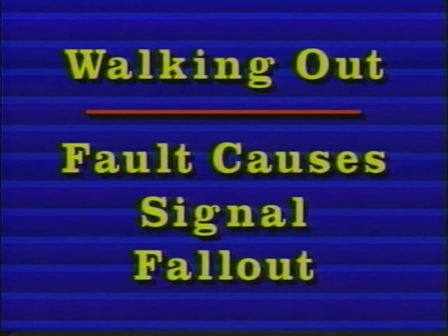Since energy will be reduced at the fault, a signal fall off will be seen by the ballistic impulse meter a few feet past the fault in most cases. When you find the spot where the meter falls off, continue past the spot 30 or 40 feet to see if the signal level comes back to where it was before the fall off took place. If the signal does not come back, you should readjust your sensitivity control for a very small meter pulse while standing just off to one side of the cable, 2 or 3 feet.